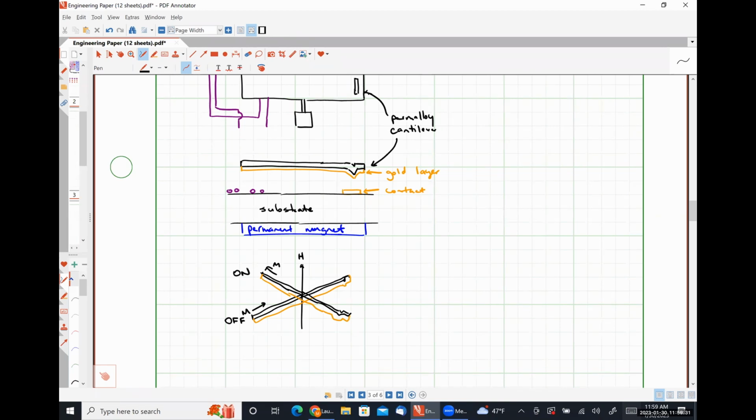Yeah, so with small wires and small traces like we would typically see in a transistor, we have a large opportunity for electromigration if the current being passed is large, because we effectively have a small area that we're passing a large current through, and it can deform because of that. For this, we have much larger contact areas, so we can handle a lot more current. And then also, we don't have to worry too much about electromigration.